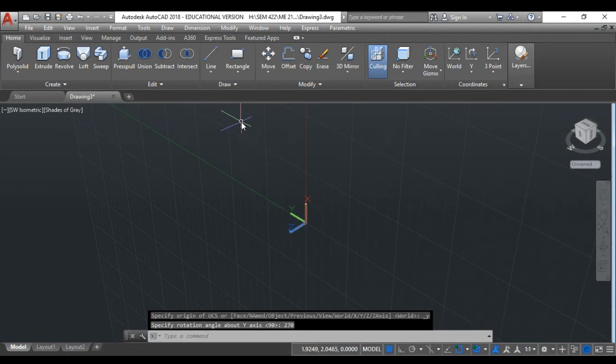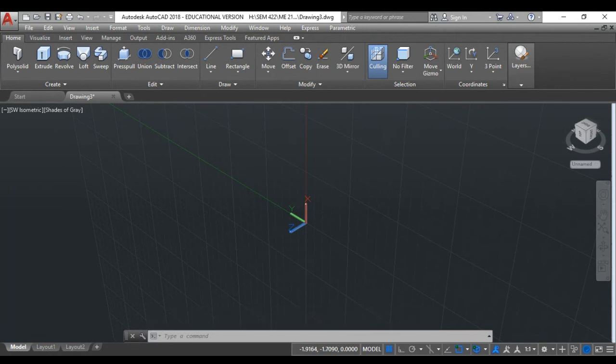Now I'm intending to draw that outer shape. I will take you back to the drawing. This side is how much? 50 by 40, right? And the thickness is 7. So I'm intending to make that 50 along the x-axis and 40 along the y. Sorry, remember, guys, we said our x becomes vertical. So our 50 will be along the y-axis, while our 40 will be along the x-axis. You see it? Okay. So now you can see the AutoCAD.